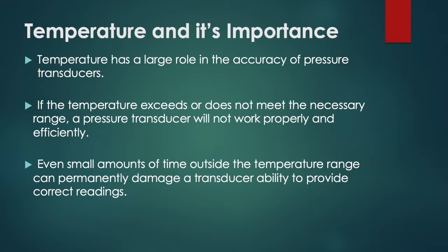Pressure transducers are used in any fluid power application requiring a high resolution and accurate electronic measurement of pressure. Used for closed-loop pump control, they can make a fixed displacement pump behave like a variable displacement pump. They can also be used as an electronic variable pressure switch. They can also take the form of a self-contained control unit, such as a programmable digital pressure switch, used to measure the pressure of a specific quantity, like a gas or liquid, by changing the pressure into electrical energy.